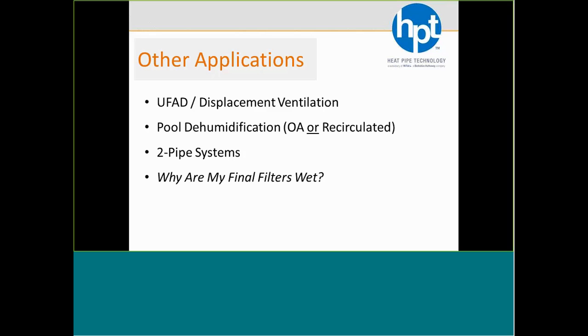So what happens then is you lose the extra reheat that the fan motor adds to the system. When the air is coming off the cooling coil, it's typically saturated, and when you add fan reheat, it pulls the air off saturation. But if it's blow-through, you don't have that extra heat. So now you have this saturated air going through these final filters, and then when it experiences the pressure drop, that saturated air condenses to a liquid and gets your filters all soaked.